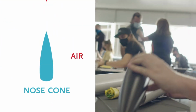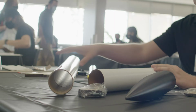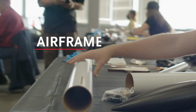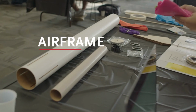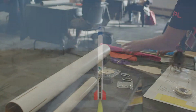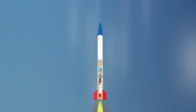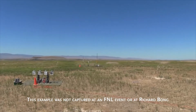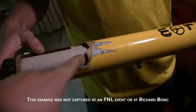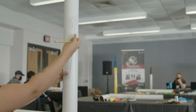The nose cone parts the air as the rocket moves up through the atmosphere. The friction of the air pushes the nose cone down, transferring force to the airframe. The airframe forms the body tube of the rocket, supporting the nose cone and fins. During flight, the airframe receives forces from multiple directions. If the rocket veers to one side or is hit by wind during the flight, the airframe can buckle or break. The airframe must be able to withstand these forces.